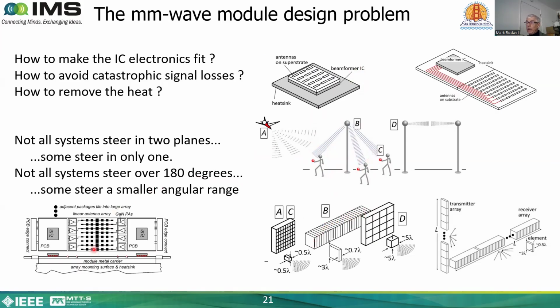In a linear array, the antennas run up and down the middle of the array, and we have plenty of room on either side of the array to put the electronics and to place large heat sinks to remove the heat. In a backhaul array, we need some degree of electronic beam steering so that it's easy to install the transmitter and receiver without aiming them too precisely, and to keep it precisely aimed as the wind blows things around.